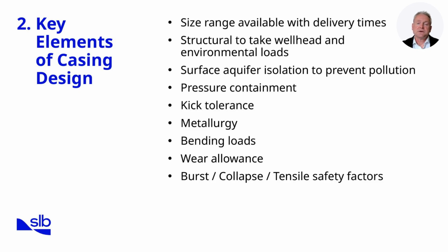We must ensure that the selected casing can safely manage expected reservoir and formation pressures, while maintaining kick tolerance for unexpected influxes. Metallurgy choices are equally important, especially in corrosive environments such as CO2 or H2S service.